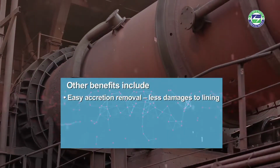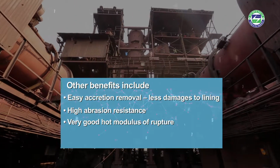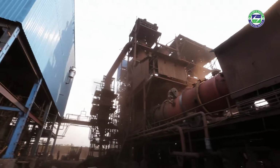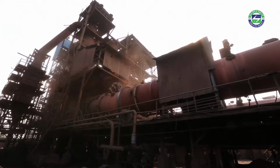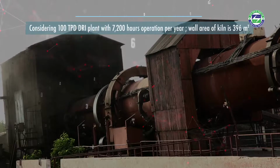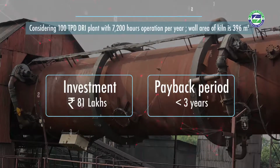Other benefits include easy accretion removal, less damage to lining, high abrasion resistance, very good hot modulus of rupture, low ferric oxide, and improved behavior under reducing conditions. Mullite-based refractory typically costs between 40,000 to 45,000 rupees per metric ton. For a 100 TPD DRI plant, 180 metric tons of mullite-based refractory is required, which works out to be rupees 81 lakhs. This can be recovered within a period of 3 years.